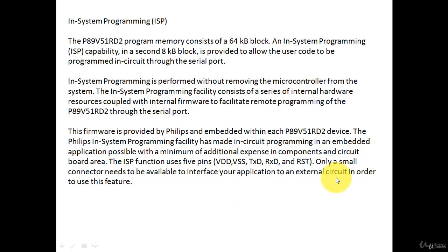In this video, to explain the complete burning process, I am using the P89V51RD2 microcontroller. In this microcontroller, there is 64 KB of flash memory and a separate 8 KB of bootloader memory. This particular microcontroller has in-system programming capability. Hence, we require only VDD, VSS, TXD, RXD and the reset pin to program the microcontroller.